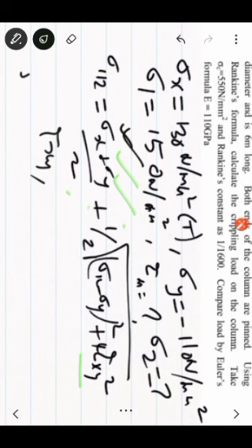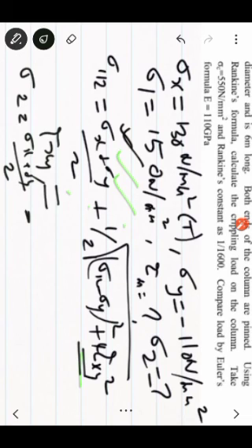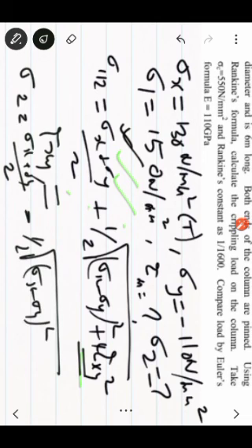Once you have determined tau xy, put it for sigma 2, just put minus here instead of plus or minus, that is sigma x plus sigma y by 2 minus half the square root of sigma x minus sigma y the whole square plus 4 tau xy square. The only unknown was tau xy, so you can get it. So the two stresses they have asked, we have substituted and obtained the answer, so that's all.